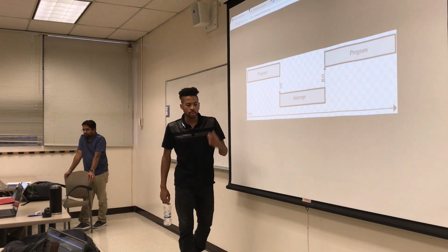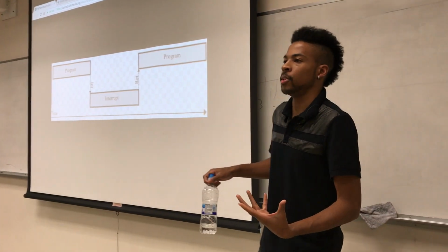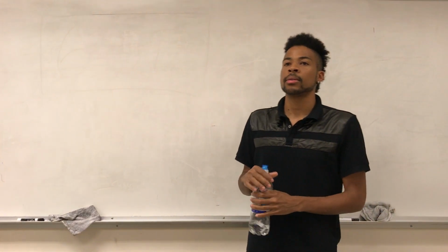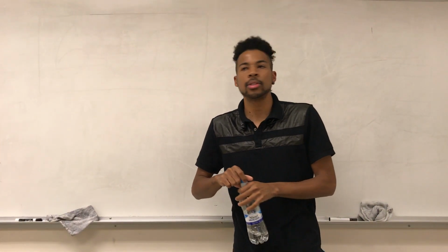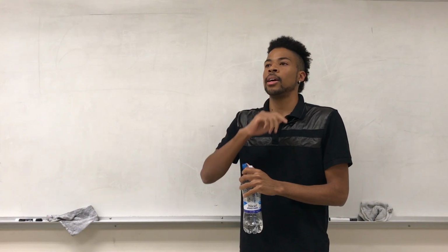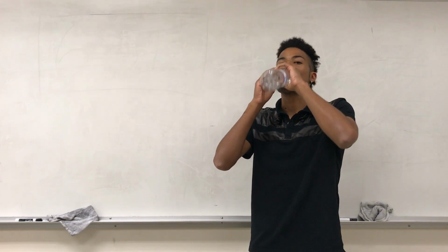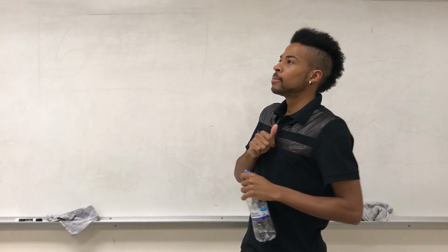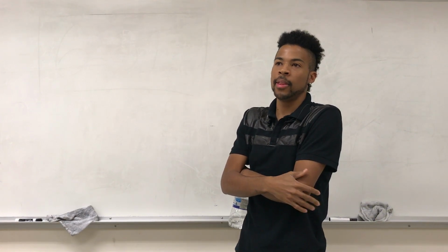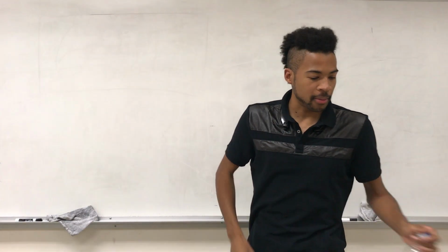Okay, so outside of the ones that we've done for lab, what are the other peripherals on the LPC that can have interrupts occur? Ethernet. Ethernet, yes. Any other ones? An analog interrupt? Yes, an analog ADC interrupt. I2C. Anything else? Quadrature encoder. Is there a module for quadrature? There might actually be in the PWM section, so I'll have to check that. But that might actually be one of them.